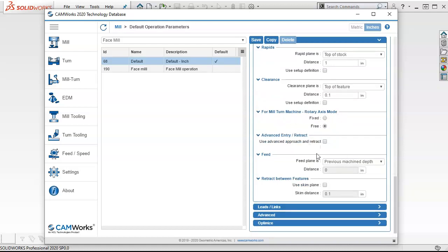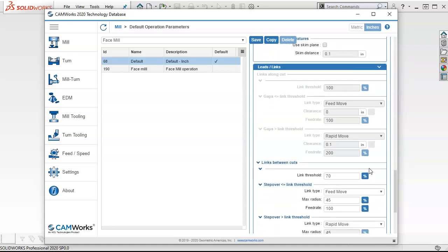We're not doing anything with the rotary. And if we want to have it pick up, like we did with the zig, instead of going all the way up to the clearance plane of 100 thousandths, we could set it, hey, you just cleared, come up 30 thousandths since we're maybe taking a 10 thousandths cut. That also has a certain amount of inherent danger in it: oh, I didn't realize that section of the part was a little bit bigger and I just rapided through it. So be careful with those rapid between features.